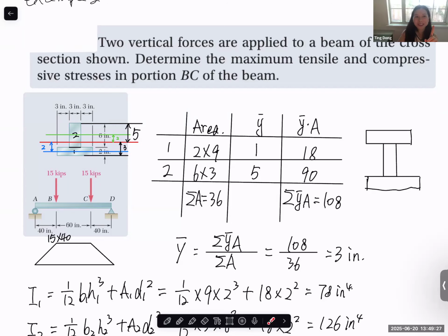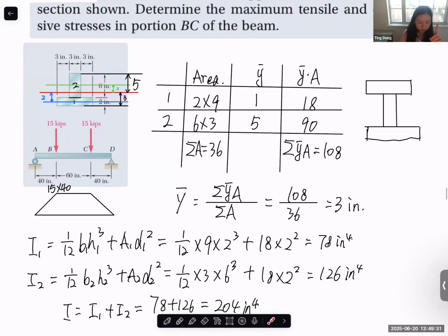What is the way you do the bending moment diagram? Let's say you want the bending moment diagram of this section, and for a random point, you cut through this point. You know the reaction force is equal to 15. Cutting through a random point, let's assume this is x, the moment is equal to 15 times x. So we know that it's a straight line.